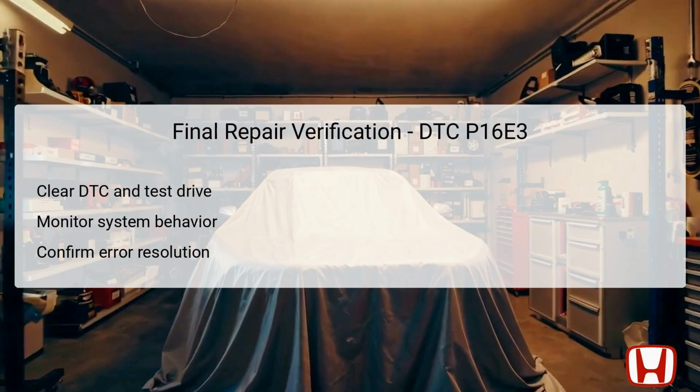During the drive, actively monitor the system behaviors to check for any recurrence of warning lights or issues related to battery monitoring. If the error code does not appear again and systems are functioning as expected, it indicates a successful resolution. Always remember to keep a detailed log of repairs and findings for future reference.